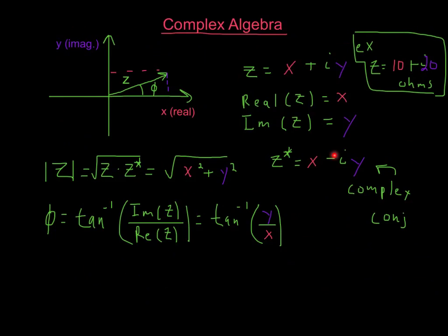this idea of the complex conjugate times the complex number in order to get something I can use in lab. This is not. But I need to know about the imaginary part in order to get the right answer. Same thing with the phase. The gain is V out over V in, and I want the magnitude of V out over V in.